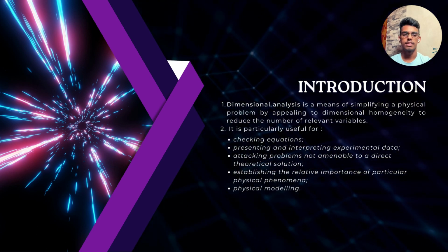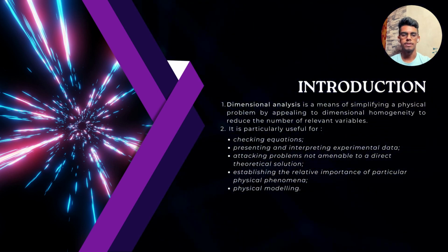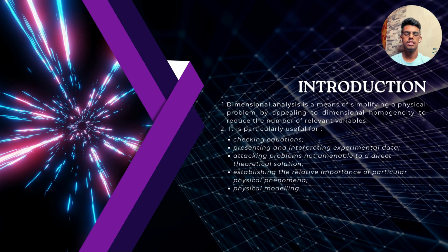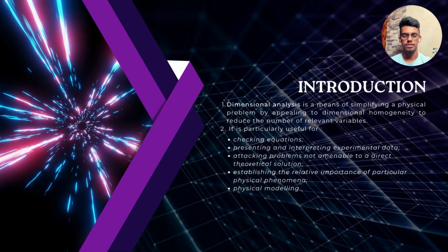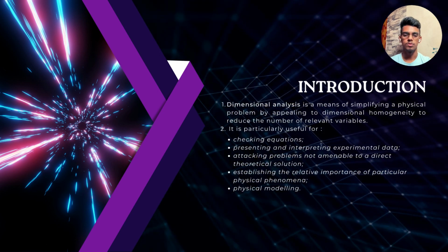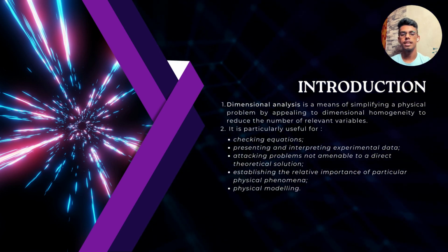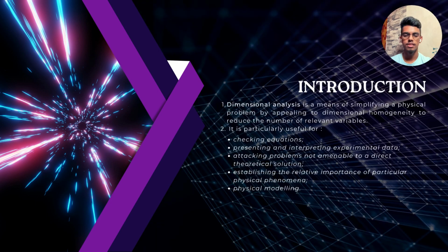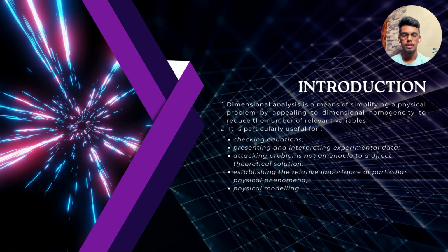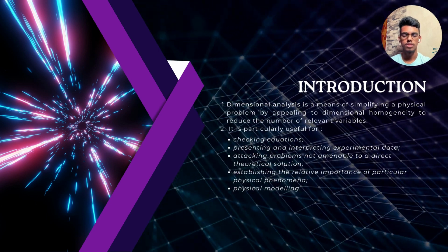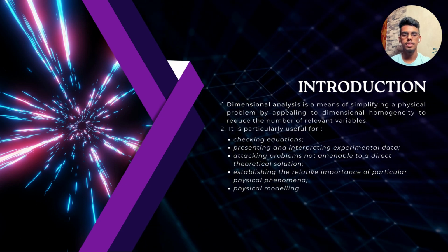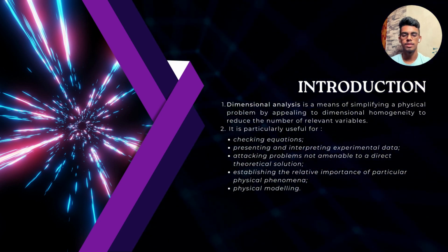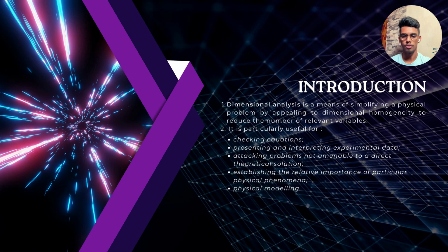Dimensional analysis is defined as simplifying a physical problem by appealing to dimensional homogeneity to reduce the number of relevant variables. Basically, it is used to check equations, present and interpret experimental data, attack problems not amenable to a direct theoretical solution, establish the relative importance of a particular physical phenomenon, and also for physical modeling.